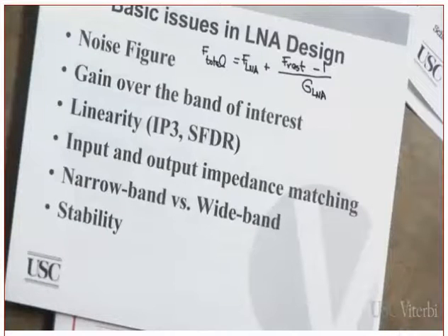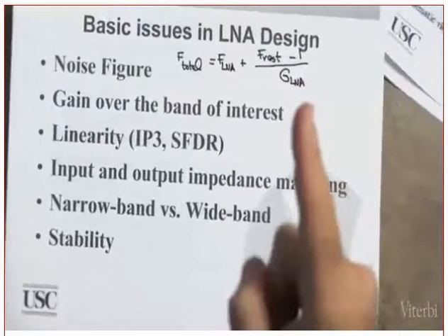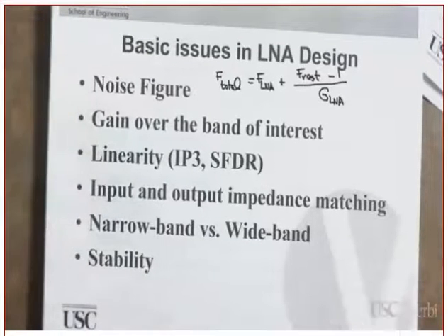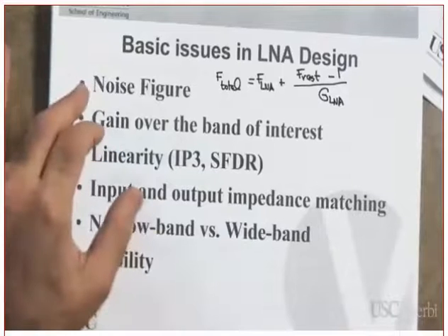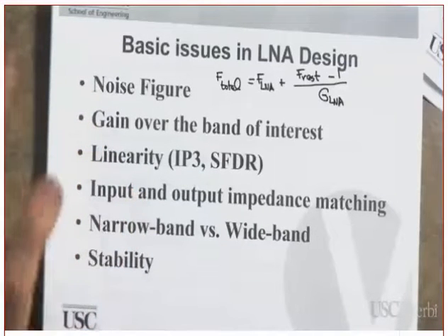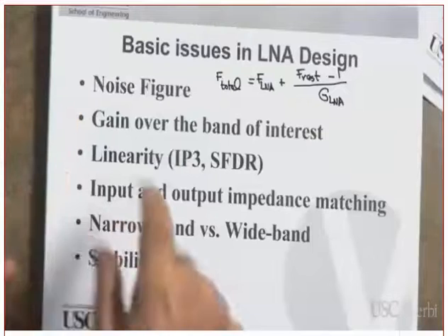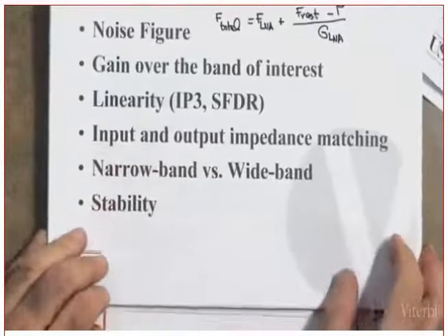Yes? We don't know what the source impedance is. Are you following me? That source impedance that results in a maximum power transfer might not be the one that results in minimum noise figure. Do you understand that or not? We need to balance these things to achieve optimization of the noise figure, and at the same time try to maximize the power transfer through the use of matching circuits.